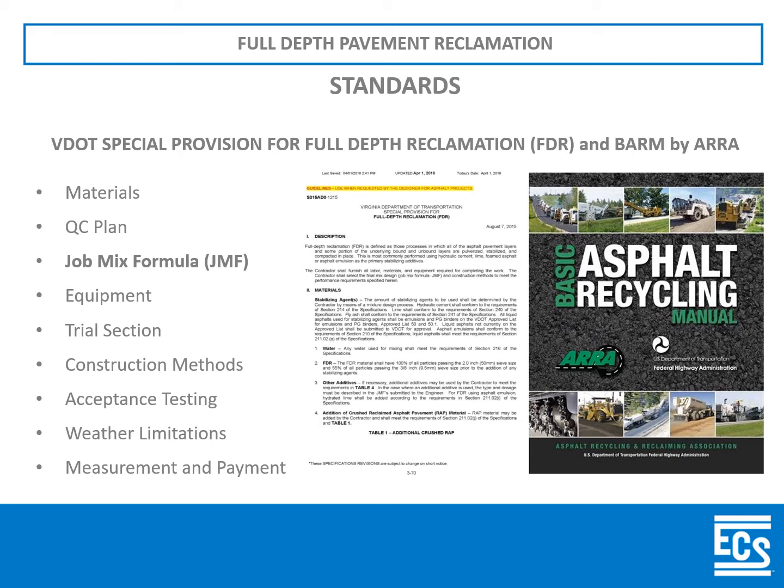The special provision section covers every aspect of what is required of a contractor or a mix design process: the materials, the QC plan, the job mix formula, which is specific to our discussion today, the types of equipment, the trial section, acceptance testing, measurement and payment. It's basically everything that is going to be required contractually in the submission process for full depth reclamation design.